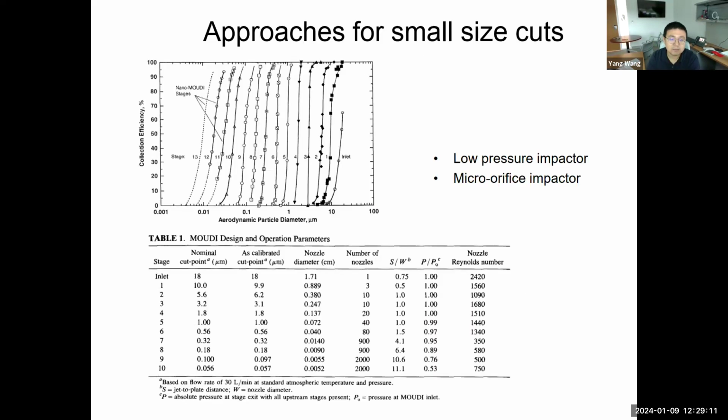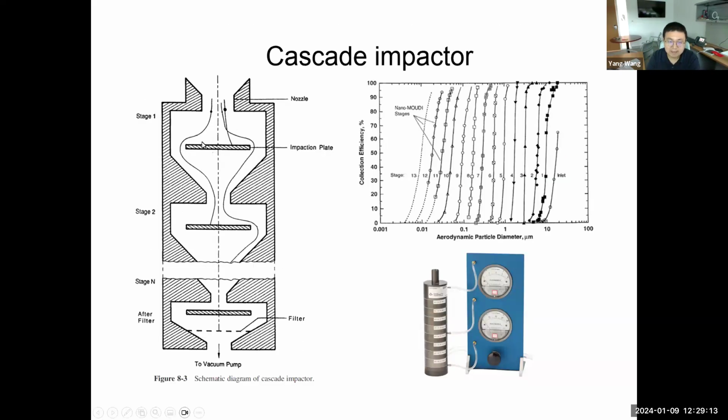So another way to characterize the aerosol size distribution with an impactor is, instead of using the cascade impactor and measuring the mass of the particles to get the concentration, you can monitor the mass increase of particles, so you can get the mass concentration of particles. But at the same time, if you charge these particles, then they can carry a certain number of electrical charges. And then if you can guide these charges out, then they will form a current, right?